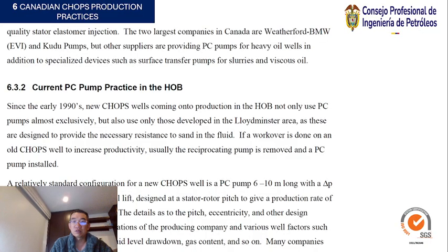If a workover is done on an old CHOPS well to increase productivity, usually the reciprocating pump is removed and the PC pump installed.